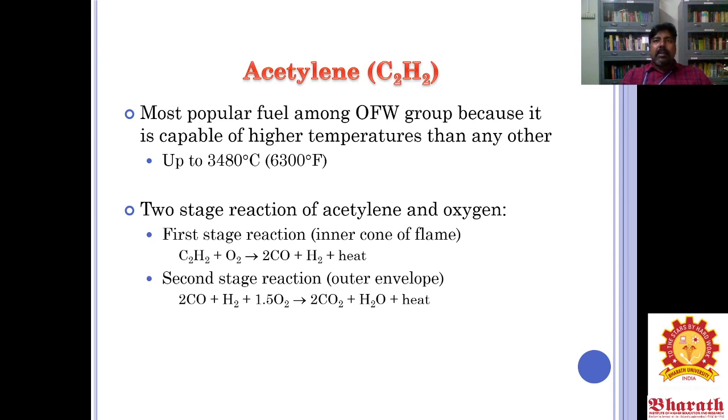The oxygen is supplied from the surrounding air, so an oxidation reaction may take place. Neutral flame we can generally use to weld steel, cast iron, copper, aluminum, etc. It has less chemical effect on the welded metal, right?